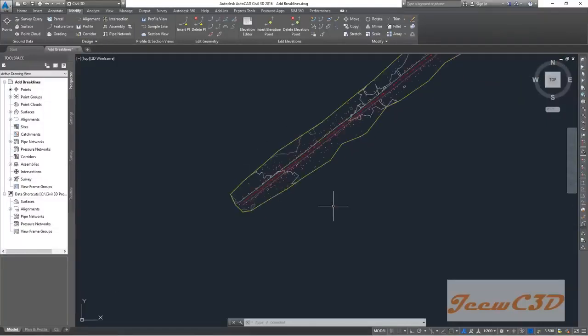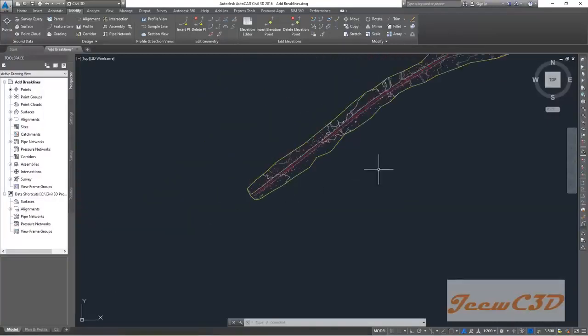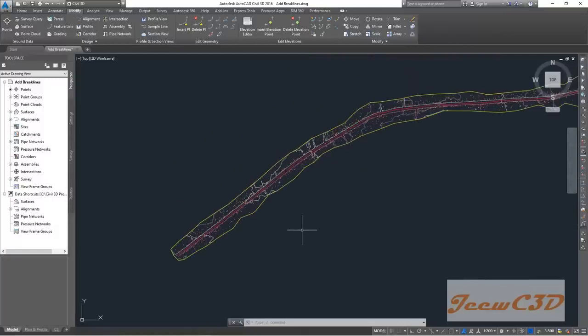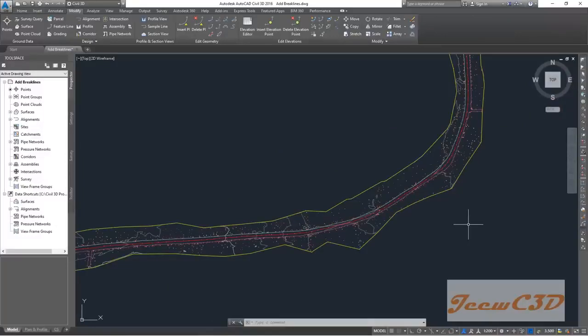But when you are working with the surface, if you see all these point data and break lines in your drawing, it will be a burden to work forward from that drawing, because you will see all these things inside the drawing and you can't properly work. So in that case, what we do is export this surface to Land XML or some other version, and make the surface more user friendly so that we can work without much trouble from the data inside the surface.